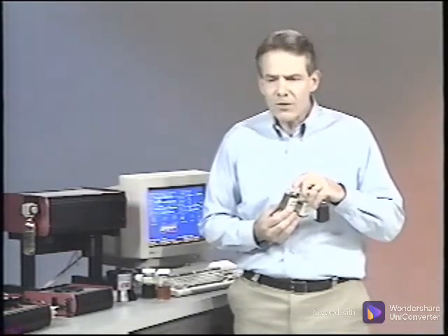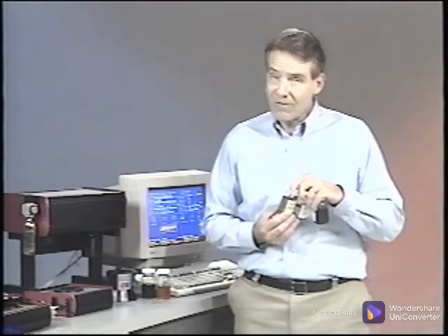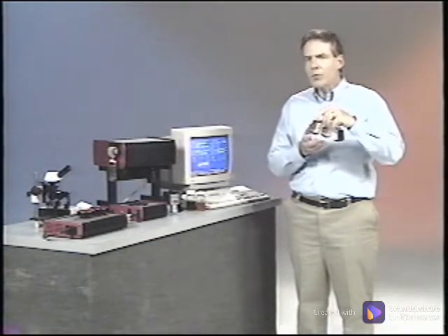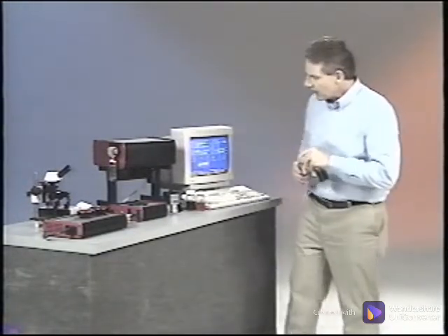Oil analysis can be compared to the analysis of blood samples in the medical profession. If all that's needed is blood type, then one simple in-office test is performed. However, there are over 900 specialized tests for blood to determine the presence of particular antibodies and diseases, germs, chemicals, and bacteria. But usually only a few tests are run on any person, with the most advanced tests being performed in an off-site lab. Machinery lubricants can be analyzed similarly, and for each machine, there may be only a few tests required. And like blood tests, an instrument produces specific results, so many instruments may be required for multiple tests.